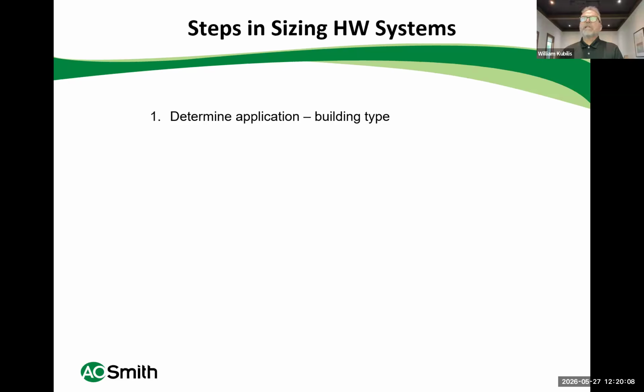There isn't really any particular case where you have to go to tank type. For example, we just did a project where they put 30 tankless water heaters in one building. So we just keep adding to them if that's what you want. If you don't want storage and you go tankless, that works. I do have a couple of examples, though, moving on here, of when it might, at some point, not make sense to put tankless in, and tank type water heaters are better. So maybe at the end, if I haven't answered that, we can come back to that question.